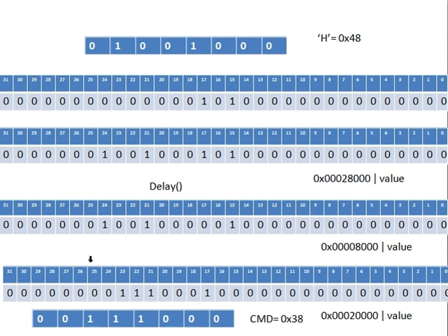So you cannot place the data anywhere in this FIO pin register. This is your FIO pin register, and FIO pin register of GPIO1 we are using. So we will be using LPC GPIO1, and there we take the register FIO pin, and there we need to shift the data by 18 bits, so it goes to the pins 18 to 25, which is actually the space reserved for storing this data.